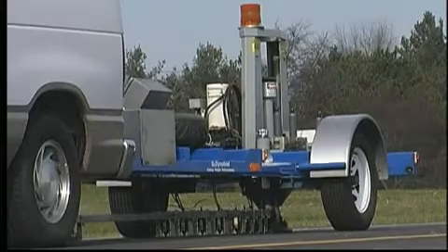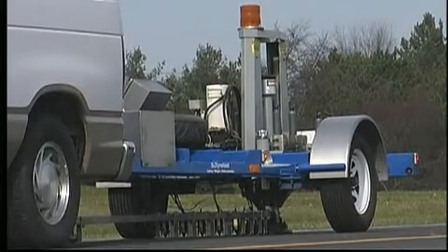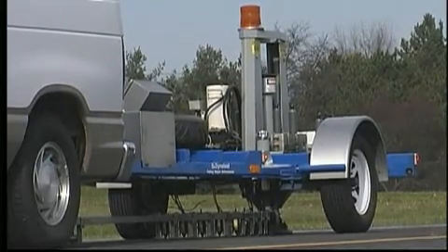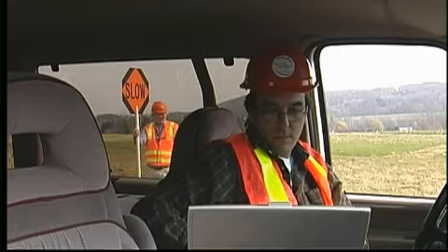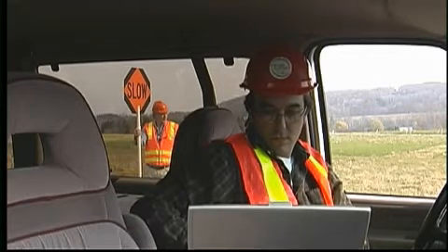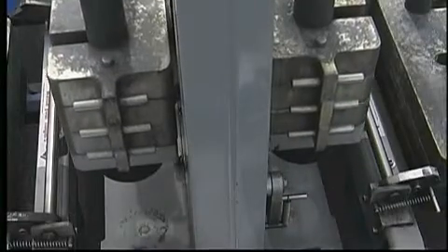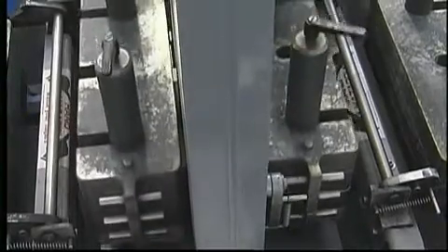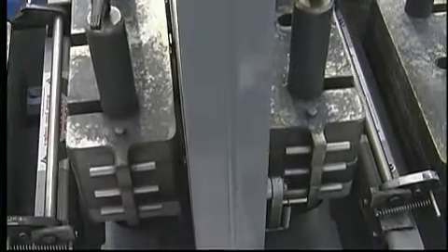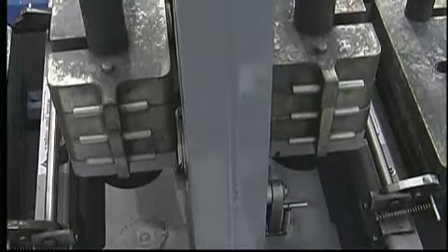The speed of the FWD allows an agency to go down the pavement and test multiple points fairly quickly with limited amounts of time needed for traffic control, which is very expensive. The FWD can help determine the expected response of the pavement surface, and to some extent the response beneath the surface due to the passage of trucks and other large vehicles.